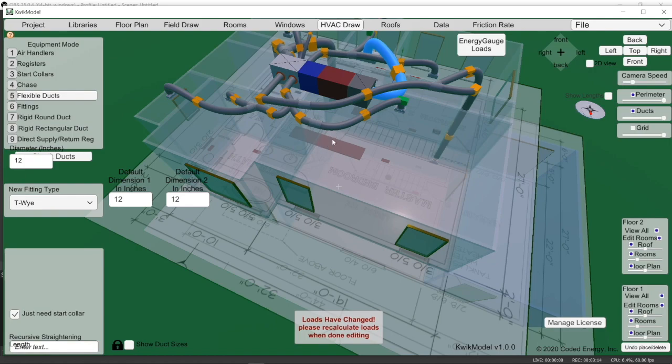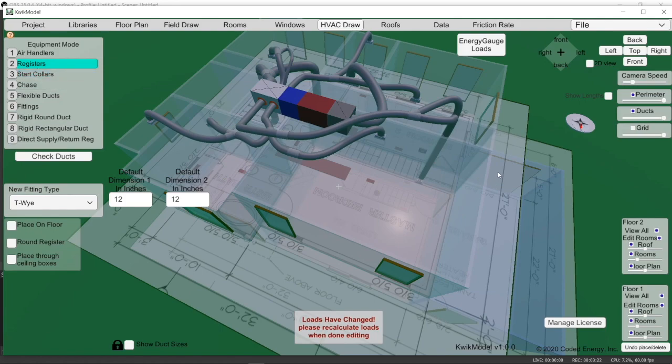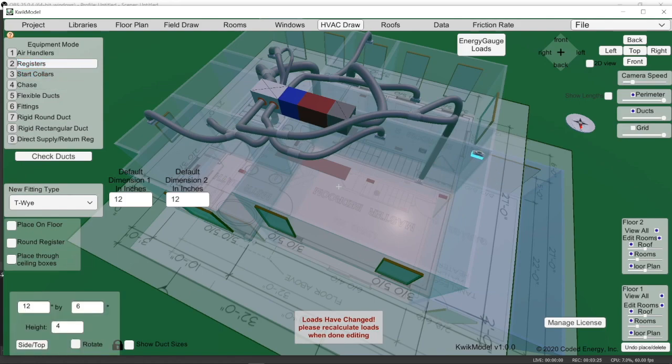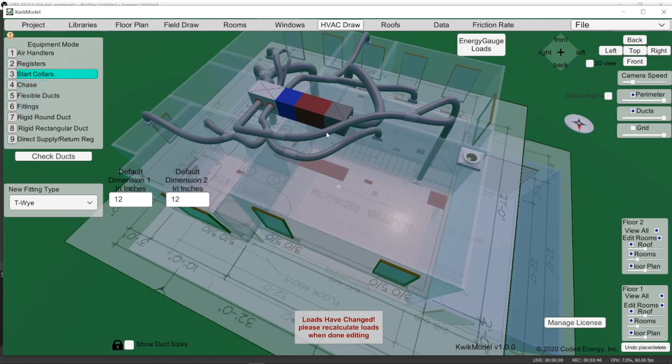And if we were to expect all that air to go out under that door, that's just too much, okay? So I'm going to go ahead and put another return grill, and I'm going to tuck it in this corner, and I can do the calculations later, but I'm going to make sure it's a nice big grill. I'm going to put a 24 by 24 in there so that it's quiet. It's inside the master bedroom, so you want it to be quiet. And I'm just going to come right off the top.